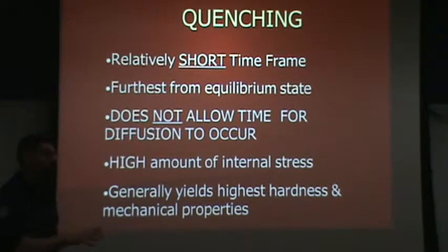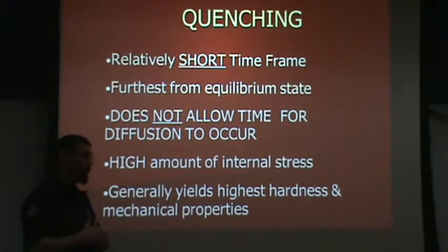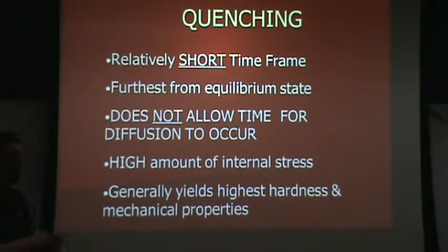Most of the grain refiners, aluminum nitride being the primary one, don't dissolve until you get over about 1800, maybe 1830 degrees. So as long as you keep your temperature under that, you will always have aluminum nitride. In the case of the steels that I work with, you'll always have aluminum nitride present to serve as a grain refiner.